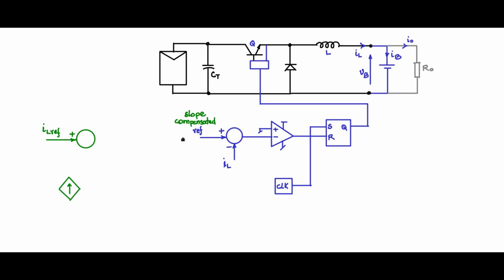So let me have a controlled current source. This controlled current source will have a current value I, which is dependent on the sensed value of Vb divided by L into Cs. So put a capacitance there, and across the capacitance I will put a switch, and this switch I will turn on based on this clock signal. So whenever the clock gives a high, this will turn the switch on and reset this capacitor, and then when this goes off, the capacitor will start integrating.